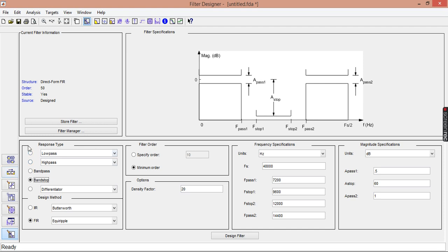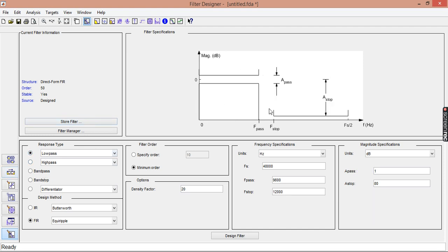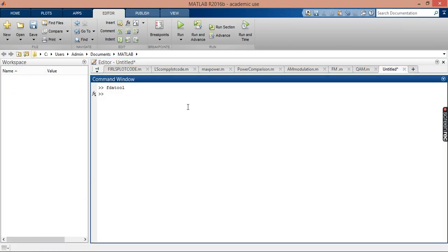Okay, so let's go ahead and design a low pass response. For example, let's say I have a signal which has frequency components, or probably I should construct a hypothetical signal. Let's say a sampling frequency of 1000. Suppose I have two tone signals. Let's say f1 is 200, and another tone occurs at 400. If I need to construct a time domain signal out of this, I need to define a time vector. So let's go ahead and do that.